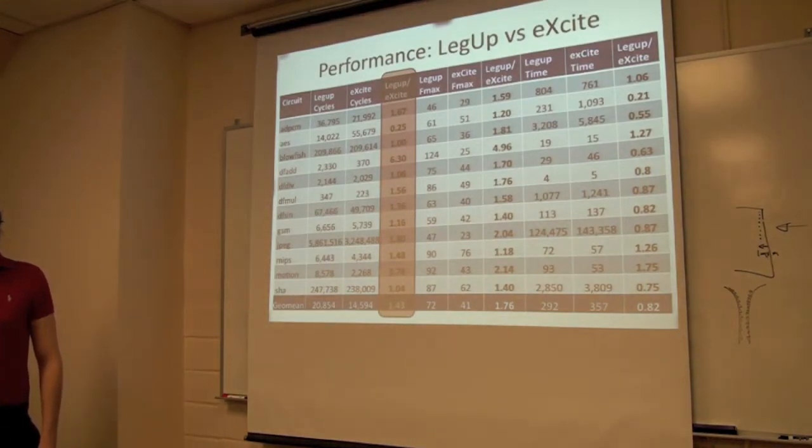We also don't have resource sharing yet, right? We have resource sharing for dividers, but it's very basic. We can squeeze a lot more. Right now there's not that much sharing, it's sort of sequential hardware. We have to share more hardware, especially the DSPs. What was happening with Cyclone 2 was that the DSPs were limiting us. By sharing multipliers a little bit smarter, you can probably reduce the DSPs if you're coming close to the device maximum.